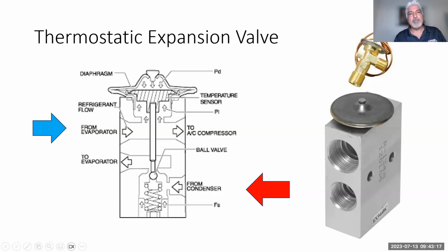So if you have a compressor that's locked up, it grenaded, you take it apart and it's metal, you need to understand that what probably took out the compressor was liquid, because the ball valve was probably stuck in too open of a state, allowing too much refrigerant. So as much as we use the expansion valve to control the flow of the refrigerant and get the best efficiency in the evaporator, it also ensures that there is nothing but vapor going back to the compressor.